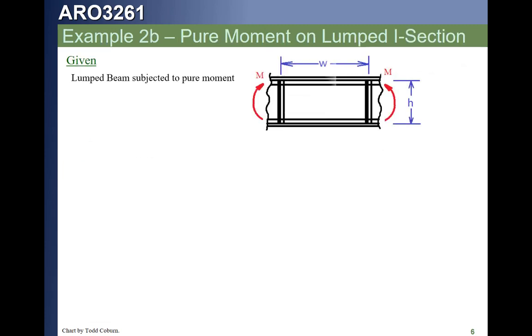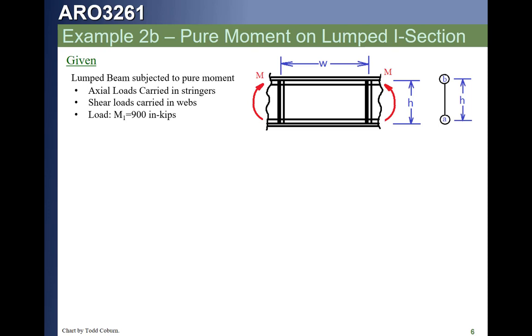So if we look at our beam, this is what we saw before. The other picture was actually looking at the end of it. What we saw was our 2 lumped areas before, as shown over to the right. Now, if we want to draw an exploded free body diagram, that means we're going to take each element of the beam, blow it apart as if somebody had exploded the thing, and then we're going to put our forces on it and work our way through the structure to figure out what all the forces in all the members are.